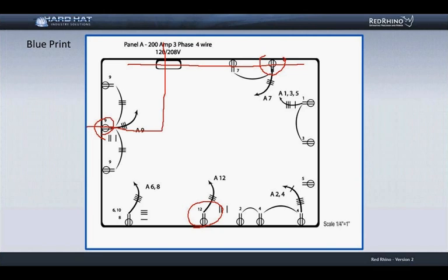I do not need to take off couplings, connectors, or supports. Red Rhino will add those materials for us. It's important to understand that I measure and write down on the takeoff sheet the total run length of all runs of the same size and number of conductors. Next, I write the footage calculated by the scale X on the takeoff sheet, reset the scale X to 0, and get ready to measure the next run.